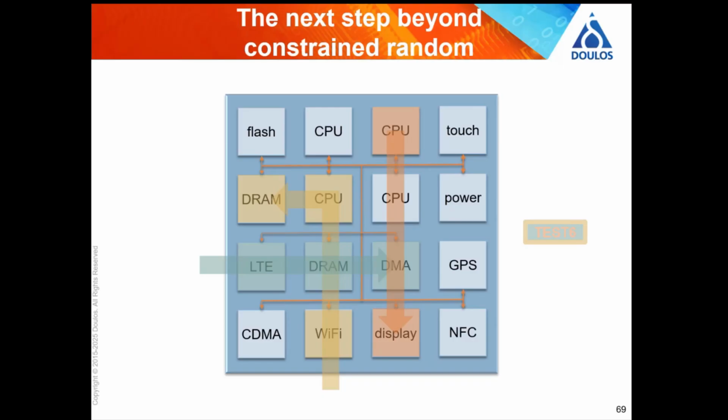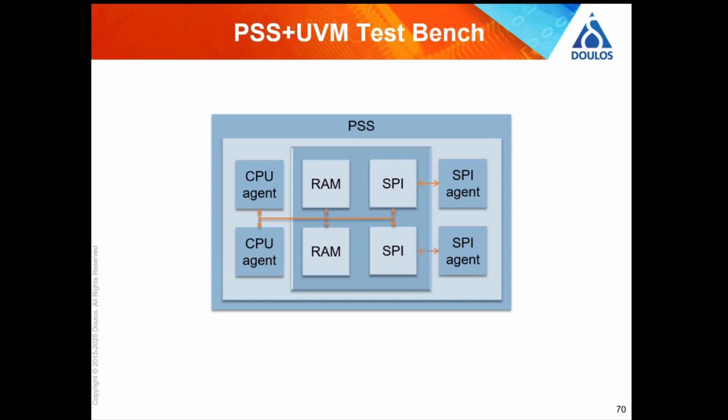It's another level of randomization. It's not just randomizing details about the test. The whole idea of the test is random. So I'm just going to show you a bit of PSS code, and I'm going to use a simpler DUT because otherwise your brain will explode.